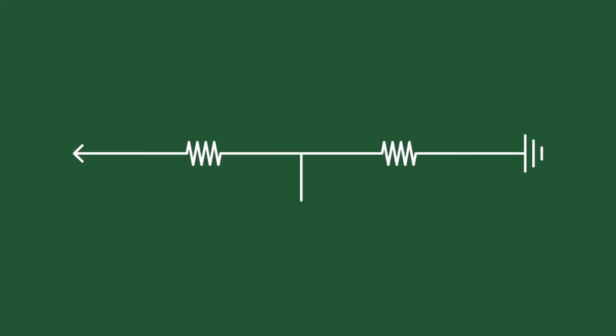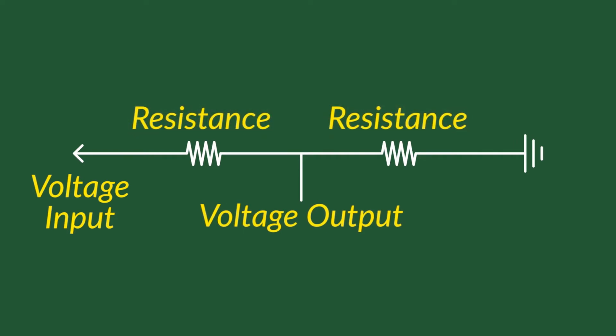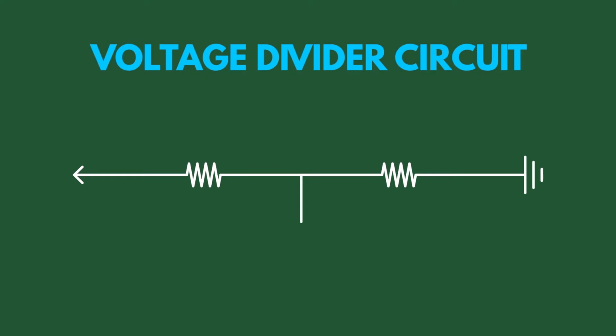Temperature sensor is a device that measures the hotness or coldness of an object. In an Arduino microcontroller, the sensor reads a 5V input voltage and changes its voltage output depending on the resistance change in the thermistor. A voltage divider circuit uses two resistors to create a mathematically predictable voltage value, Vout. R1 is the thermistor and it changes relative to temperature and hence changes the Vout generated by the sensor to give temperature readings for the microcontroller.